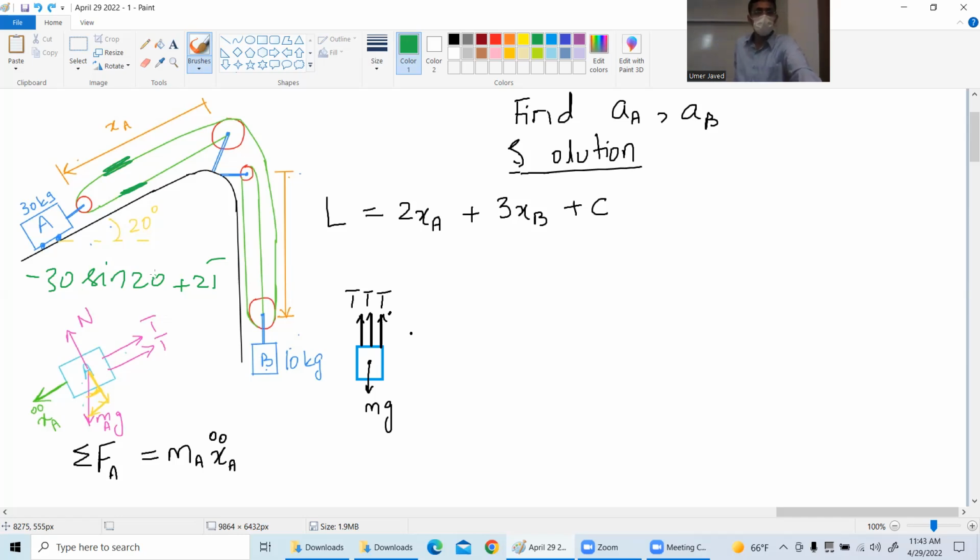So yeah, I think both of you are fine. 30 multiplied by sine 20 gives me 10.2. Now, 10.2 in any case is greater than 10. My point is that this object will be sliding downward. Are you getting my point? Both of you, all four of you. Okay.